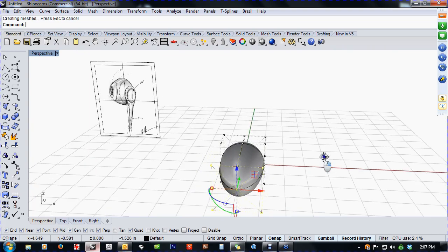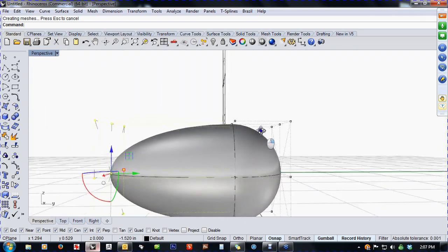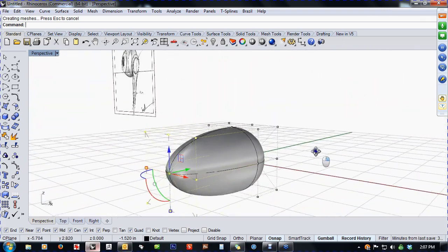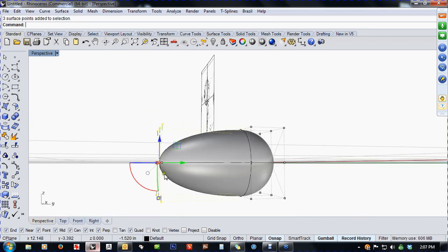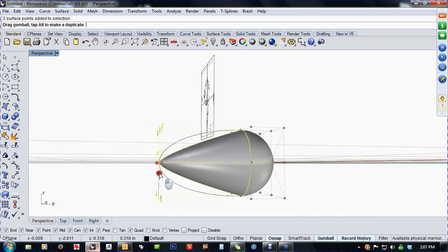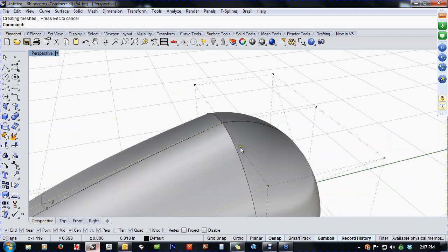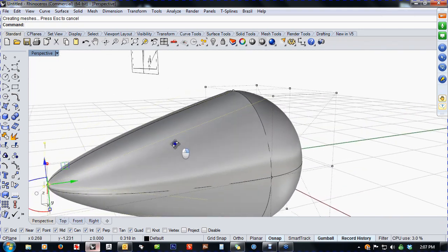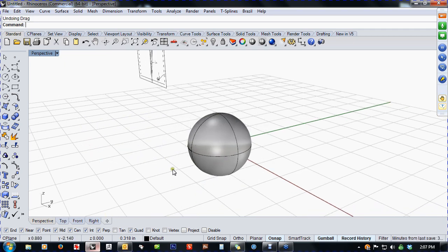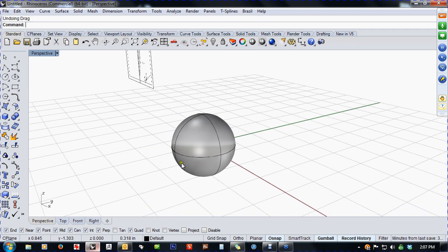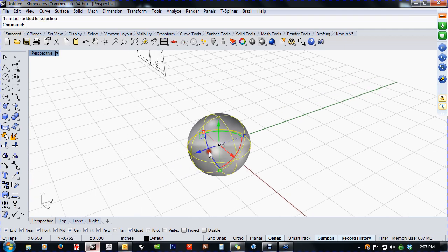It looks like I'm getting a fairly good result, but it's not quite as smooth as I would like, and it becomes really apparent if I try to scale this. You'll notice that it's just kind of sharp. It's not flowing smoothly, and that's because the initial primitive has a degree of 2. So I don't quite have enough points to do what I want to do.